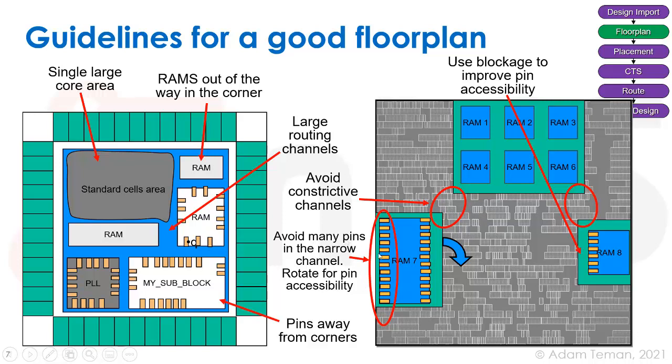Avoid many pins in the narrow channel. So this is a kind of a problematic thing. We have all these pins here that are right next to the edge. It's going to be hard to connect to.